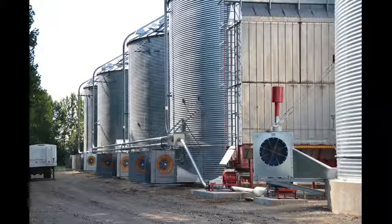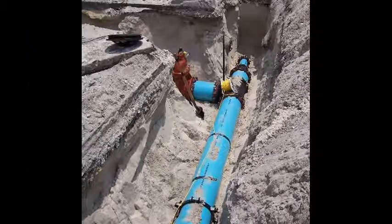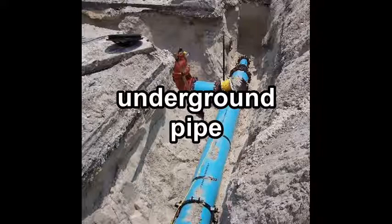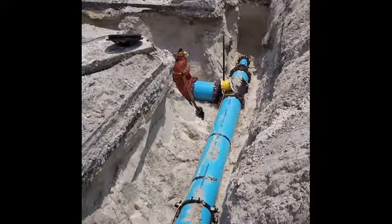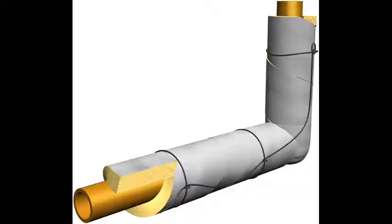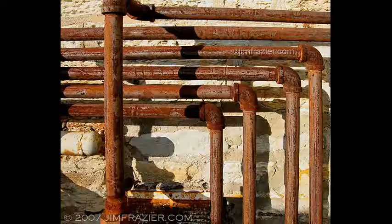If the air main comes in contact with outside air temperatures, like mains connecting or crossing two buildings, or perhaps being fitted underground, it will serve as a moisture producer, and provisions must be provided to overcome this condition. As many mains are iron pipe, rust is the eventual byproduct. Careful examination should be made when using older pipes to create a new airline.